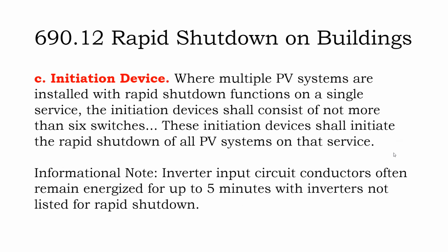But anyway, there aren't that many solar shingle products out there to begin with. So you have an initiation device. This initiation device cannot be more than 6 switches. It follows the 6-handle rule. It needs to start the shutdown. And